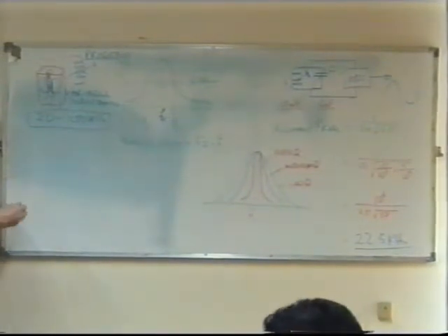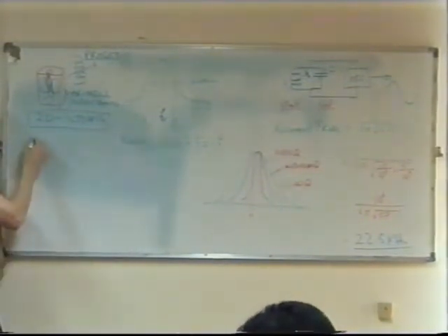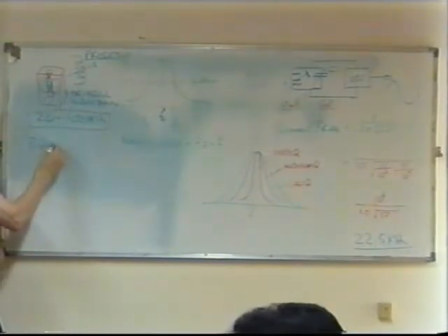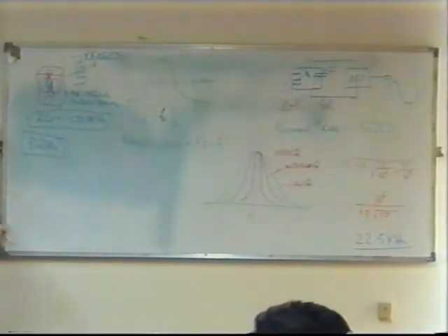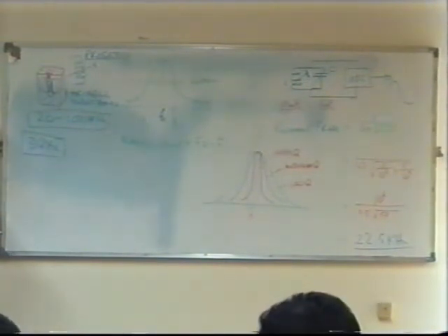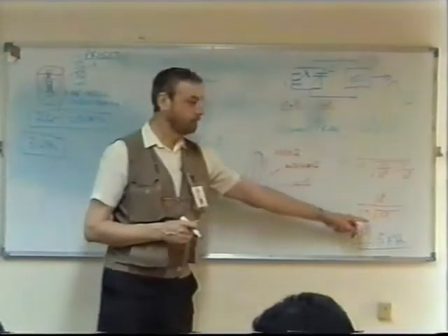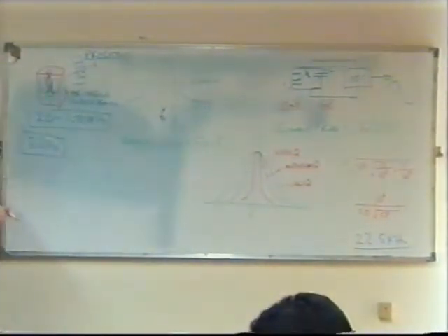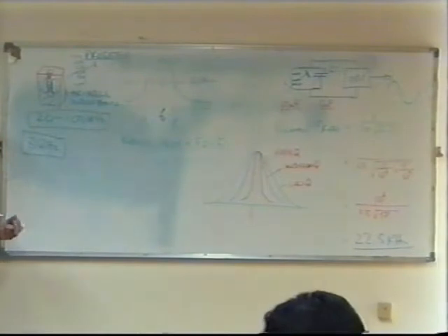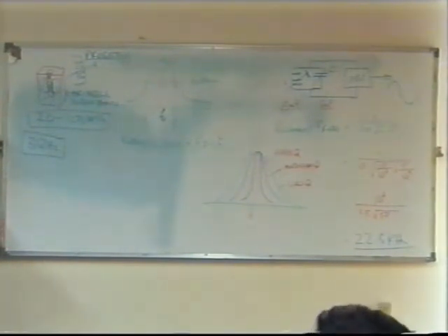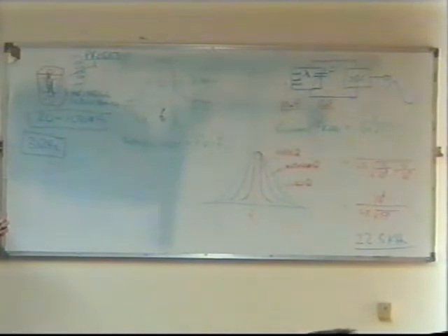Okay, so let's say we have a frequency of, say, 3 gigahertz. No, more than 3 giga to 30 giga. Yes, an SHF band, I think 3 gig is the lower end of the SHF band. So anyway, let's take 3 gigahertz as an example. We can actually use this formula the other way around to find out what values of inductance and capacitance we need to make such a circuit. And if you did that, you'll find you're talking about almost picohenries. The values of L and C are exceptionally small.